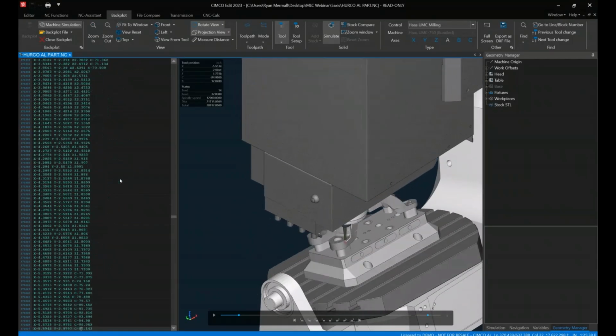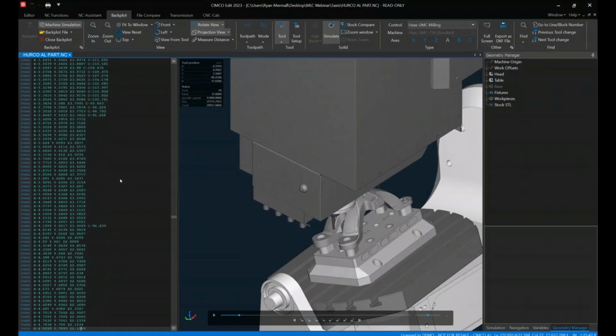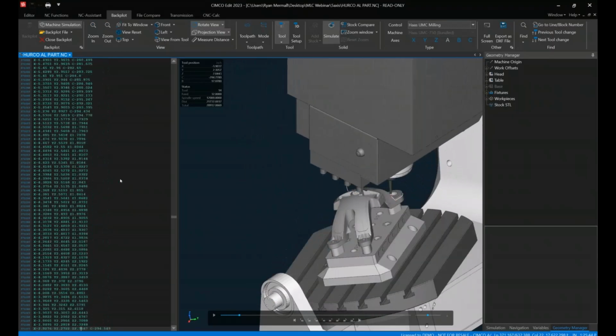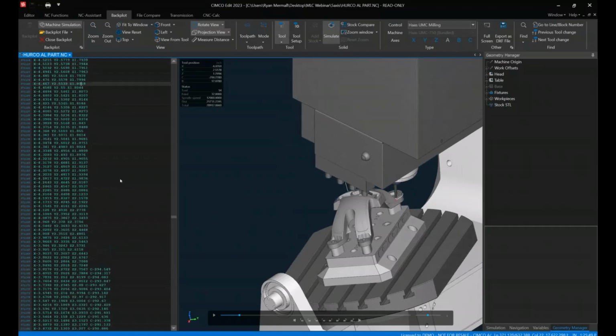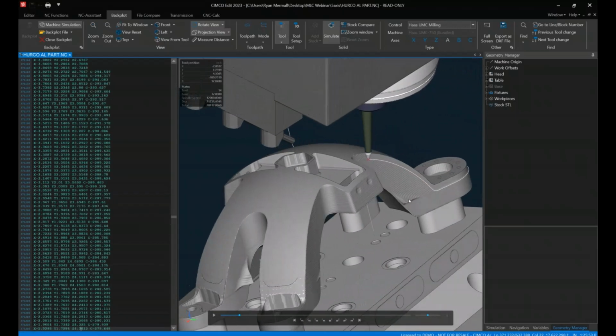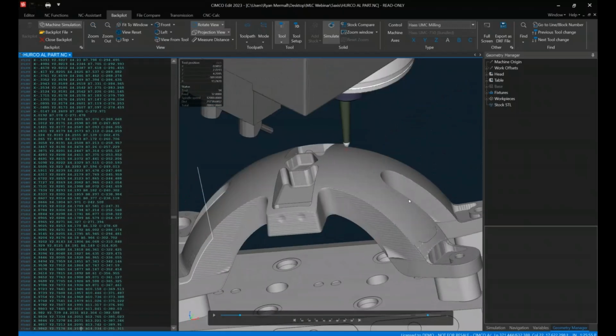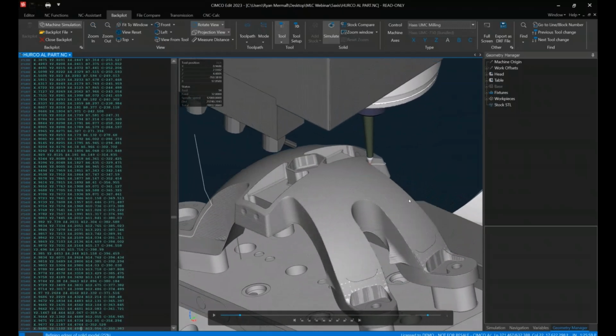And then we could certainly play that through and do some simultaneous 5-axis motion and movement as well. And you can step that line by line if you want and actually see if there's a specific area of the part you want to check, especially with a roughing toolpath up to this point not being able to clear out these areas. Again, just different areas that we could certainly do that with.